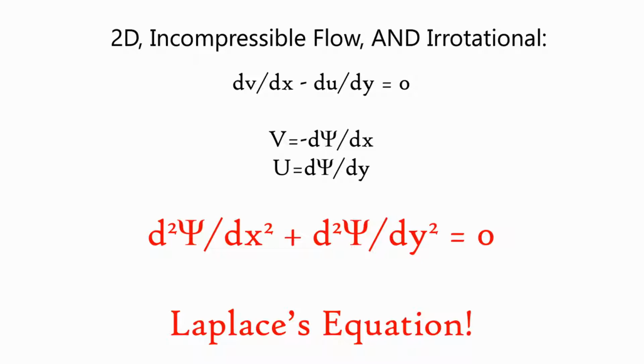Even though now we have the differential equation, we're not actually going to solve for psi like you normally would solve a differential equation by integration or separation of variables or some other method. We're actually going to use known solutions of psi for simple elementary flows. We can add these solutions together to form flows over more complex geometries. It's important to remember that the addition of the solutions is only permitted because the governing equation is linear.